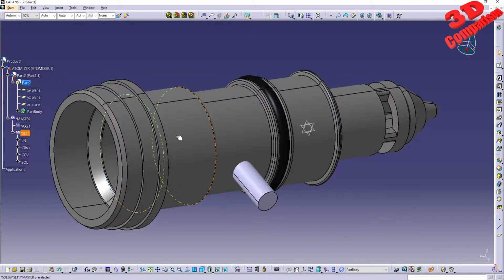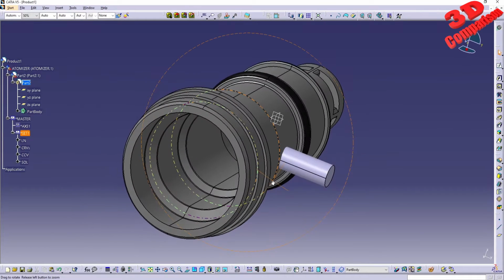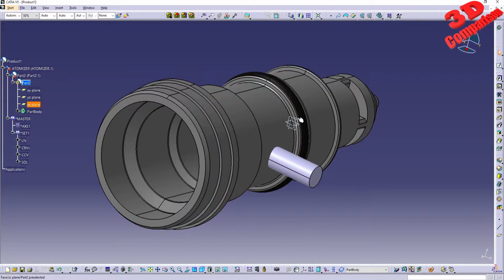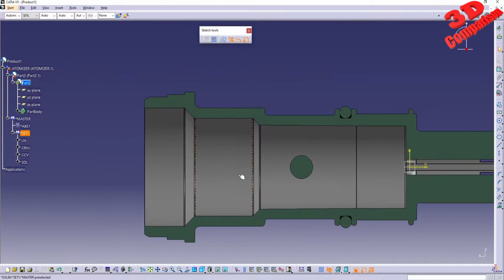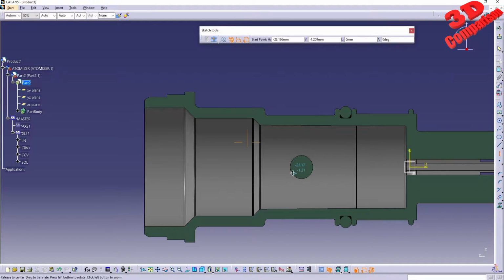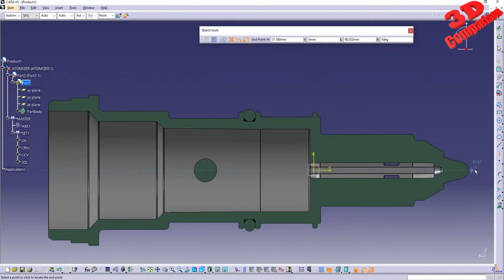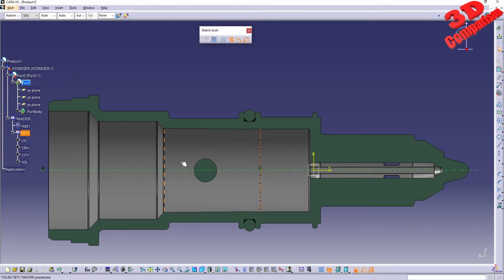Therefore, if you want to work with the geometry over here, there are some workflows that can be done. So one of those would be to go within a planar view. Afterwards, you can go to Cut Part by Sketch Plane, so this will give us a section, and we have the possibility to recreate that geometry over here.